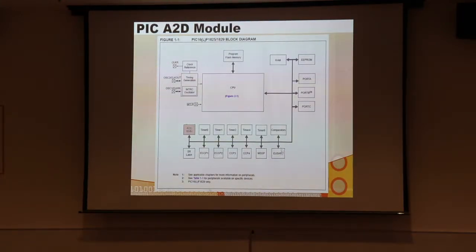There's the UART. And so we're using the UART, we're using the 10-bit ADC, and we're using CCP3 in this particular program. And some of these ports are also being used as part of the data moving in and out of these modules. Sometimes we'll use these ports just as GPIO ports, but sometimes these modules will commandeer those ports and use them for their own purposes. In the case of the ADC, you can have up to 12 of the input pins be analog inputs. And so we'll look at how this works.